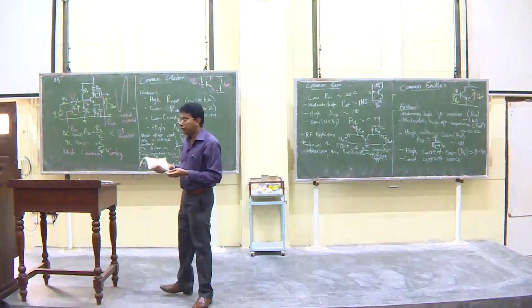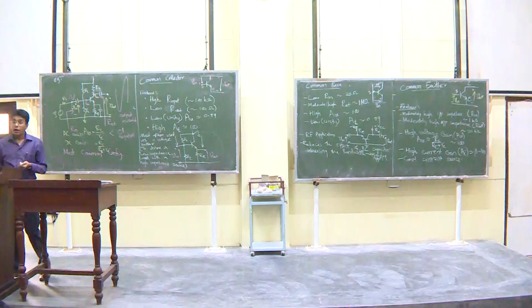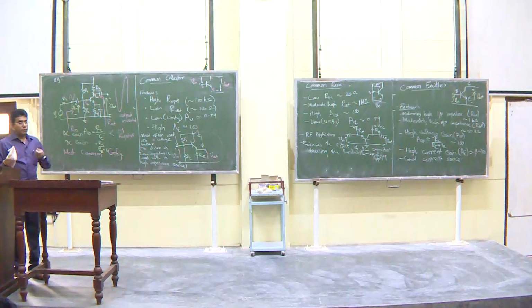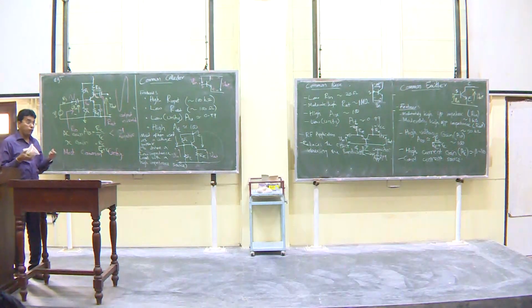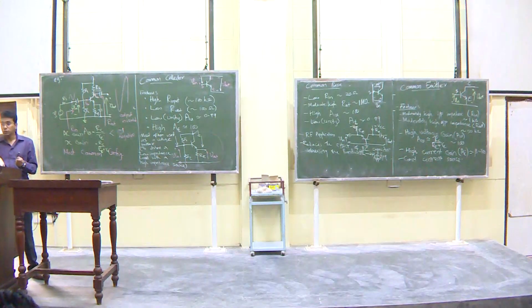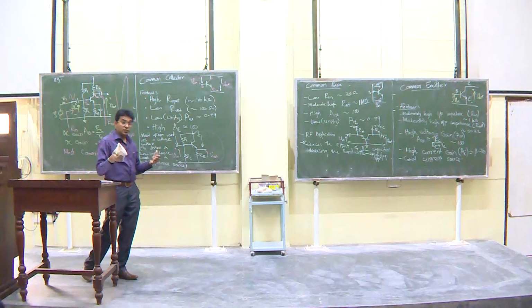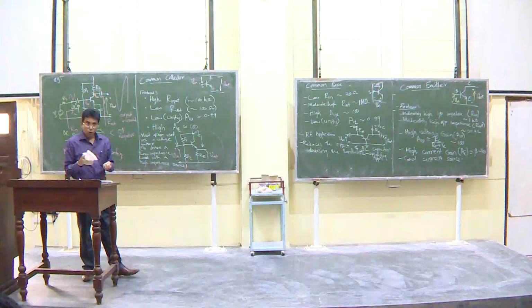So, that is a very distinct difference between BJTs and FETs. Also, FETs are much faster because of lower currents, they can be switched quickly. So, therefore, for fast applications, high frequency switching applications, digital circuits, we use MOSFETs, whereas to drive large currents, slow but large currents, we use BJTs.